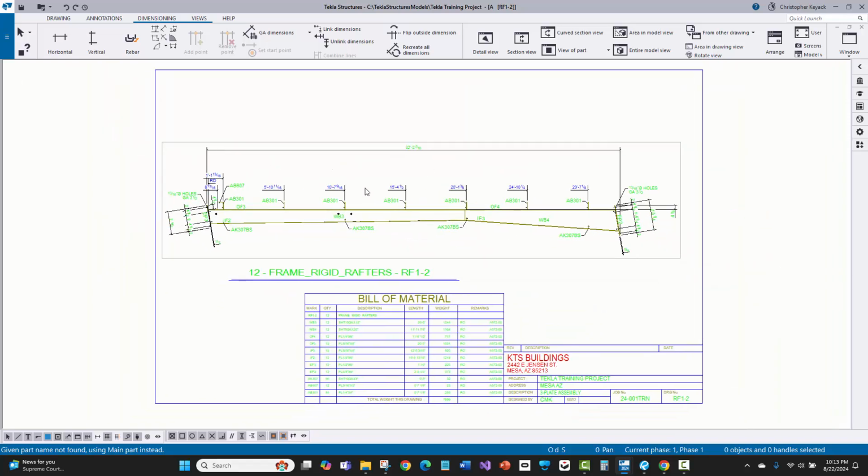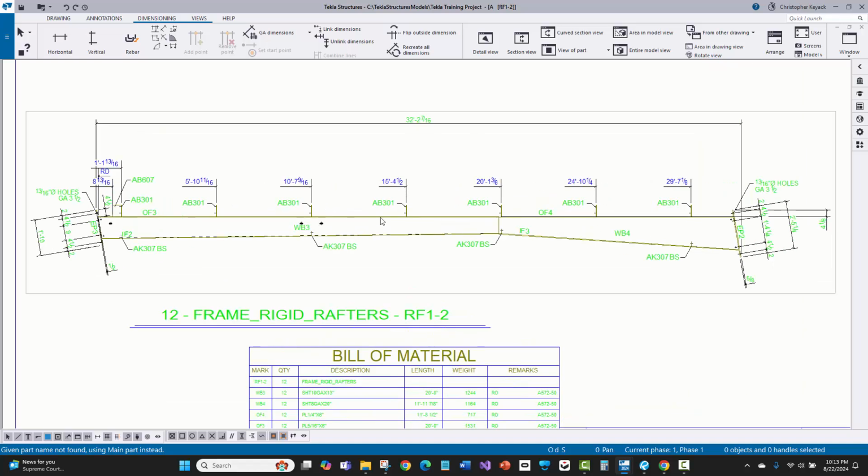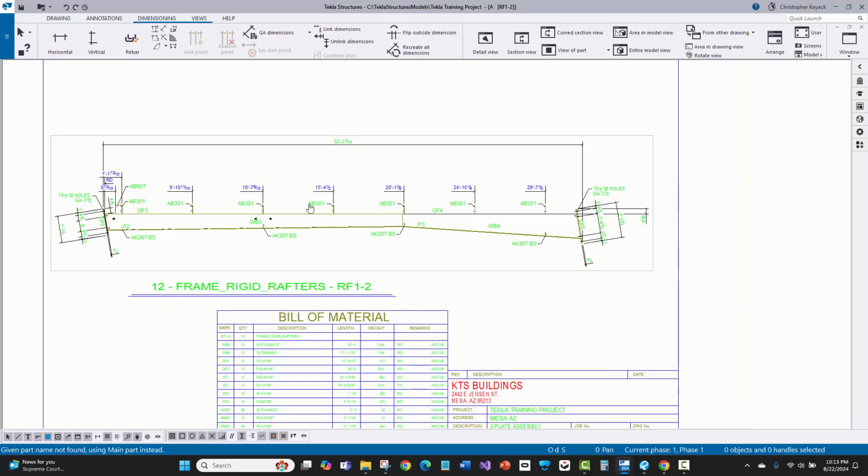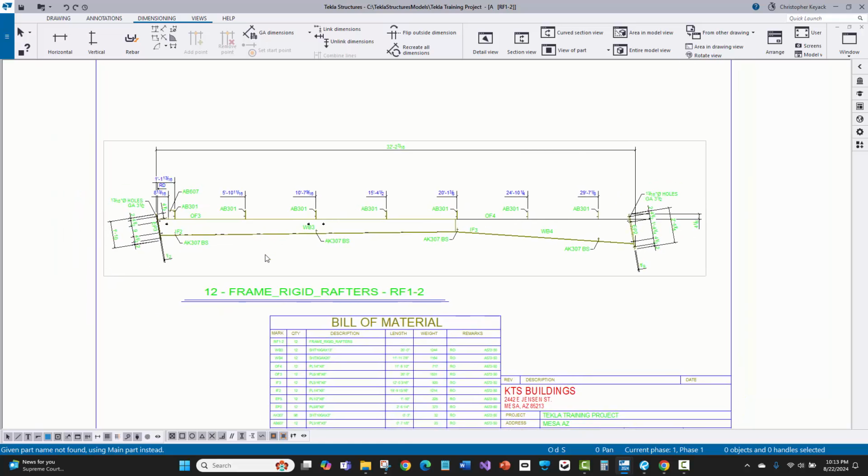And this is just, unfortunately, the nature of working with 11 by 17 shop drawings, and not having any shortening, like where we saw in the hot rolled member where it actually shortened or compressed the member and took some of the extra white space out. So first of all, let me show you what it looks like when you shorten a three plate member in order to get a better scale.